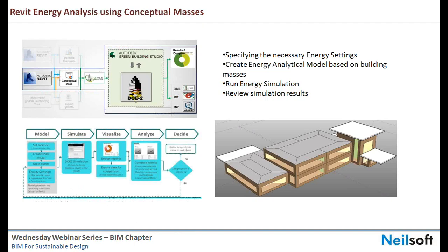Here we can see the workflow to use Revit for conceptual mass analysis. First, we have to specify the necessary energy settings, create an energy analytical model based on the building masses, run the energy simulation, and review the energy results.